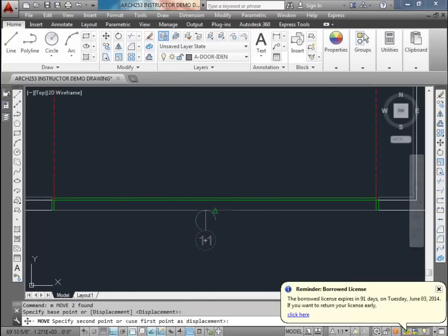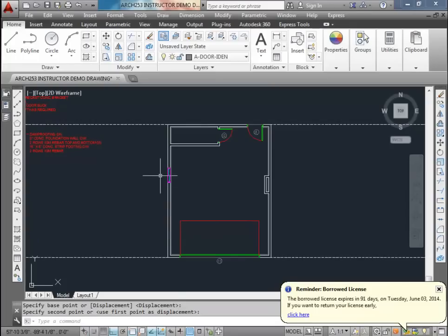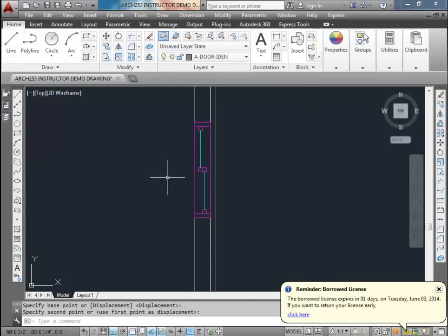And this I'm going to connect it to the midpoint. Just move it away just a wee bit. There. Alright, so we've got our door tags. Now for our window tag, we're going to be using a diamond for the window tag. And so there is a way to draw diamonds here. It's a polygon. Number of sides is 4.